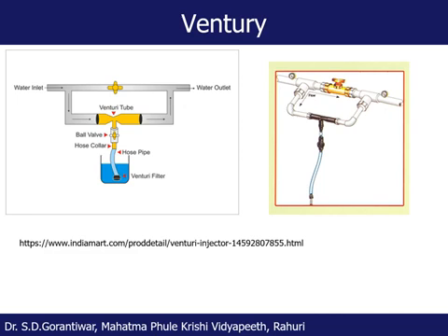And the venturi, which is most predominantly used. You see it is very easy. In this case also concentration is a problem. This venturi is based on the principle of the venturi tube. A pressure difference is needed between the inlet and the outlet of the injector, and therefore it is installed on a bypass arrangement, placed on an open container with the fertilizer solution.